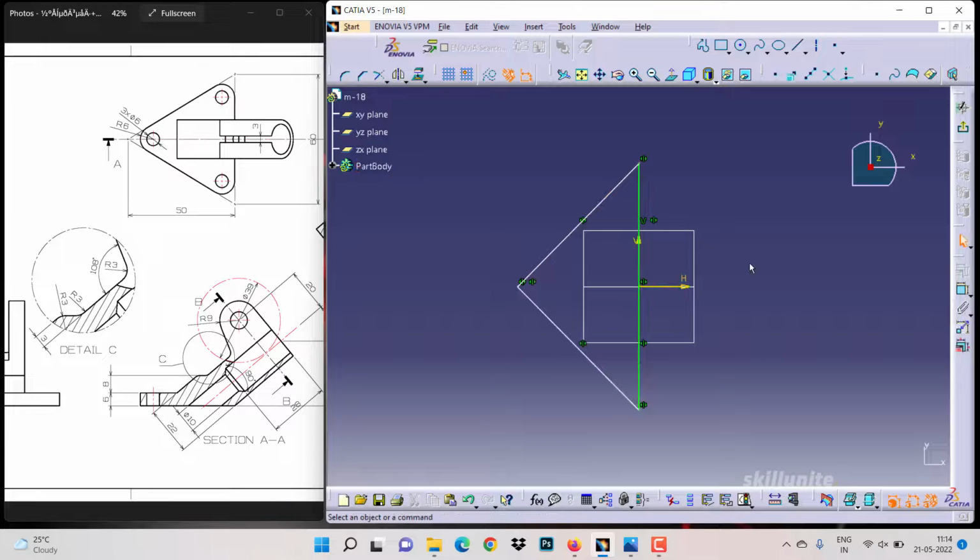Once we do the mirror, we can specify our dimensions. Before that, if you want to create a fillet, you can do that also. When we are making the fillet, the extra lines have to be there, but they need to be construction lines. Up to now we may have used the option trim all element, but now we will choose the option called construction line trim.